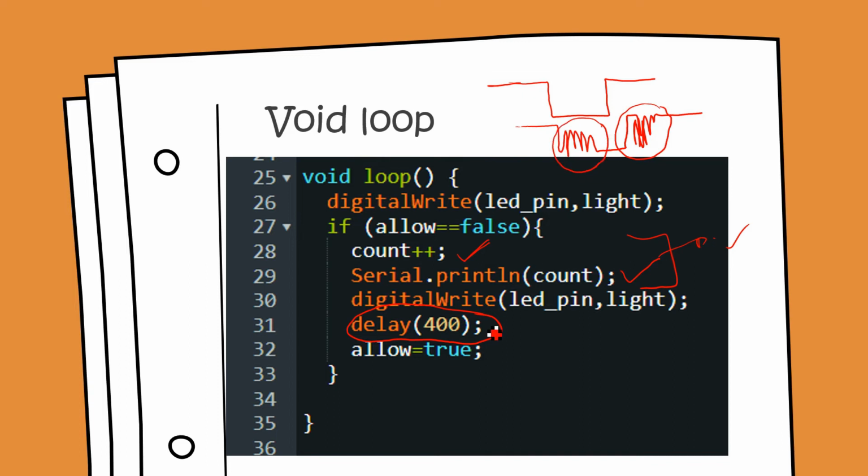This delay is basically a method called debounce. By delaying, we tell the microcontroller not to act during this period, not to take cognizance of it, and that shields us from these multiple transitions. If you skip this code, you would find that if you're not very careful in pressing the push button, you would have a few unwanted transitions happening on the LED. There are other more complicated ways to implement a switch debounce, which we'll be covering in later tutorials. So now we are ready to flash the code.